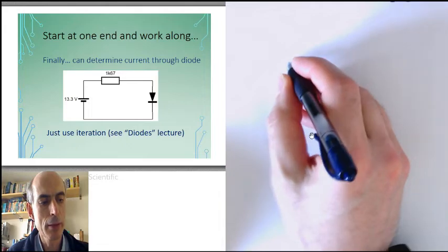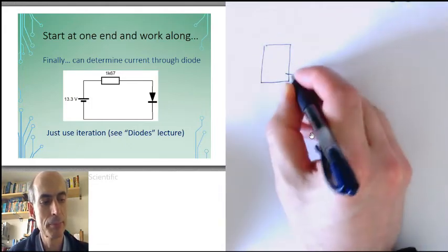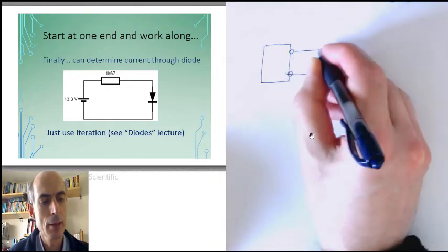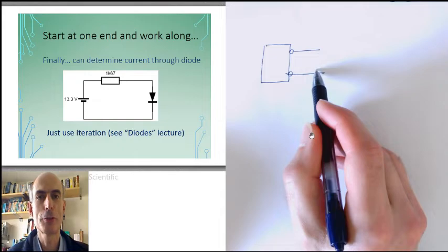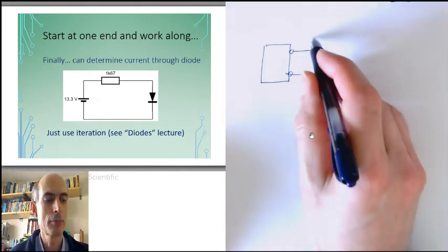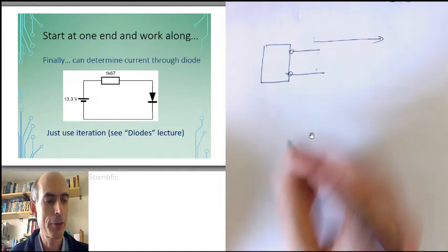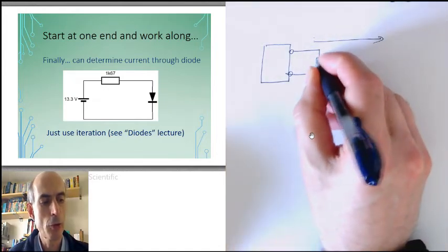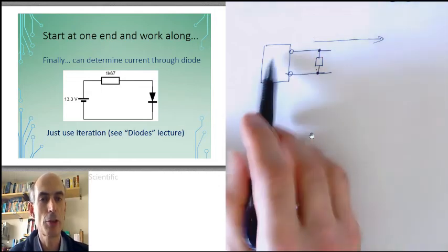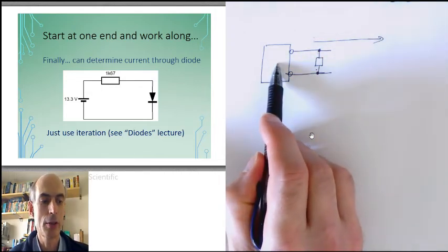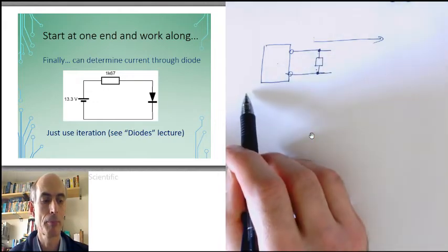The point being that if you've got a 2-terminal network here, what you do next depends on what the next component is in the chain of components going towards the other end of the circuit. If the next component is a parallel resistor like this, then you need to get a Norton equivalent circuit in here so you can combine 2 resistors in parallel.